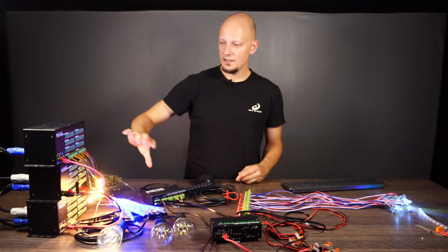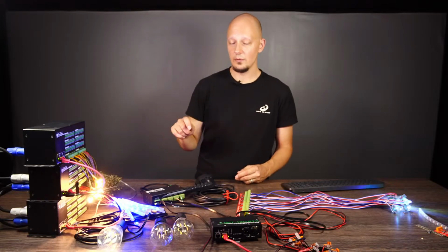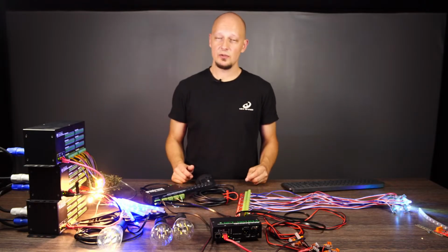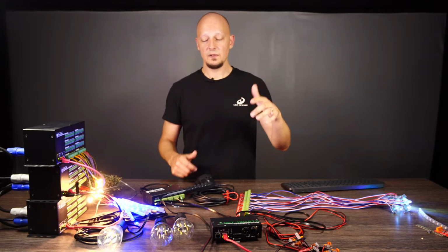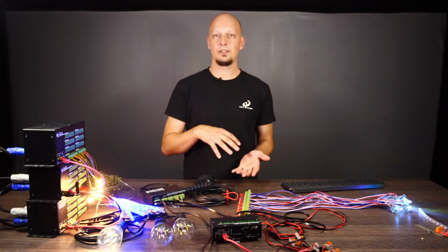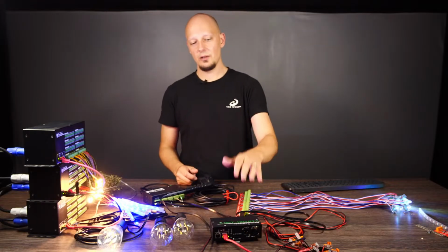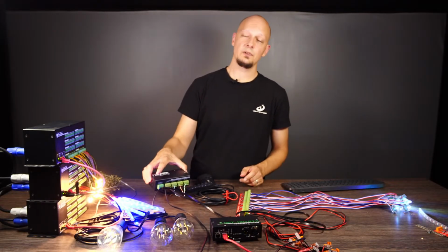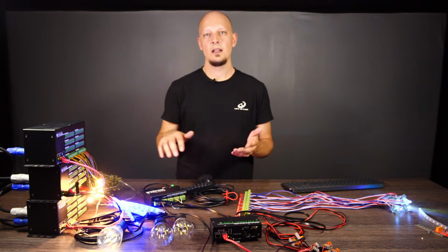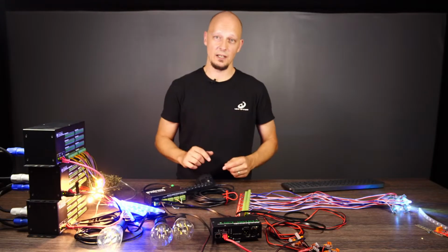I already mentioned that you can daisy chain multiple together and then use LED Strip Studio software to map everything out and send the effects or animations into your pixels. That's why I have all this on the table. You don't have to have the PC running all the time on site 24/7. You can create your effects beforehand, store them on an SD card, and then use, for example, DMX to trigger your effects. So all these can work in sync to deliver the effects that you've created in the software, and you don't need the PC running all the time.